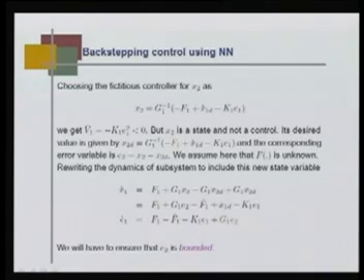So, its desired value is given by x2d. This is not a control action. What I can say is that if my x2 is following this desired value given by g1 inverse times minus f1 plus x1 desired dot minus k1 e1, then my first subsystem is stable.